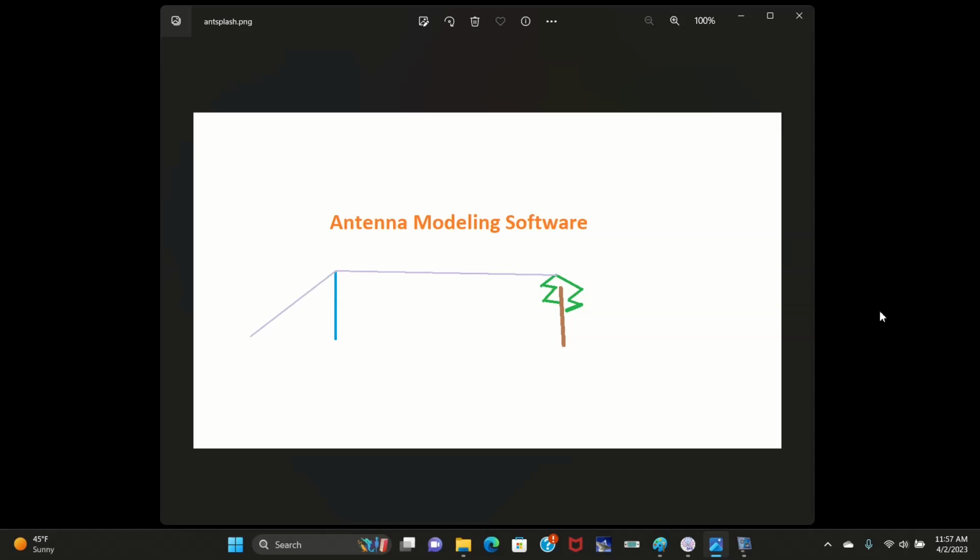and I plan to use these tools to create the perfect antenna for three different radio situations. The first one is a 40-meter dipole for a monoband QRP CW rig. In my case, it's the QCX Mini, which is a 40-meter band rig, the one that I own. It doesn't have a tuner, and we want a resonant antenna, so we don't need a balun of any kind.